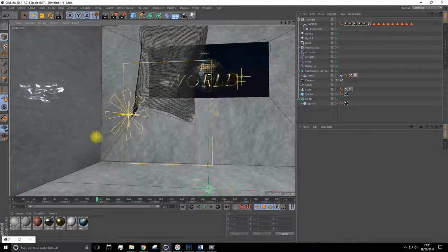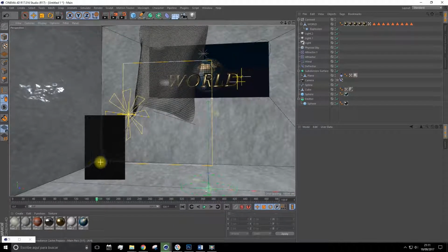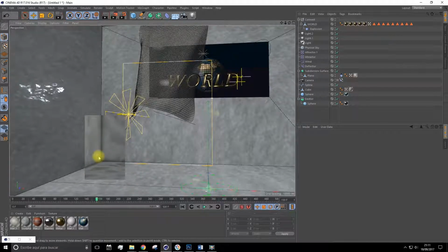So now it's activated. The ambient occlusion is the shadow that generates when two objects are close together. So if it's not activated, we won't get that. Or it's not that noticeable. But when it is activated, that shadow between the parts of the wall makes it look a lot more authentic.